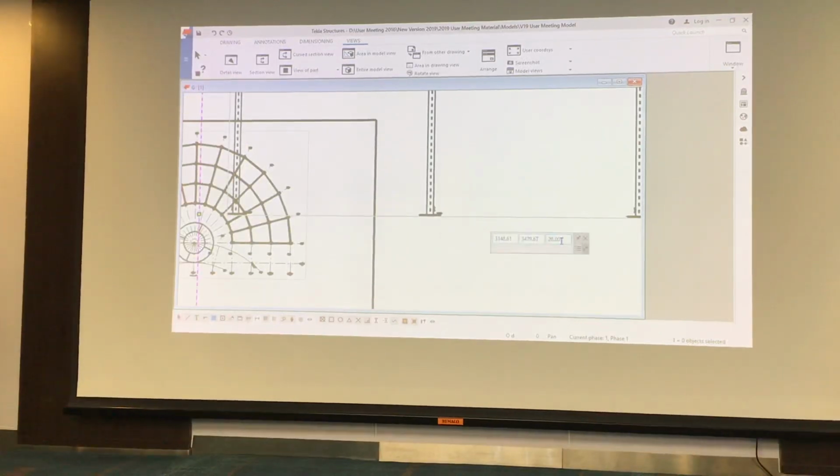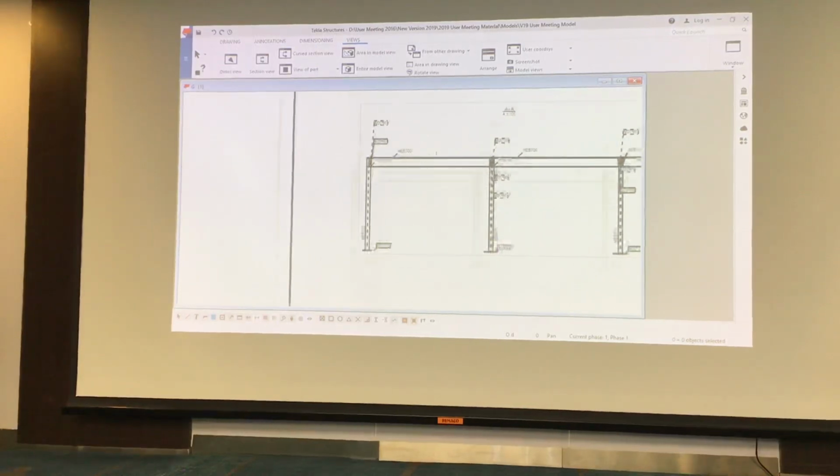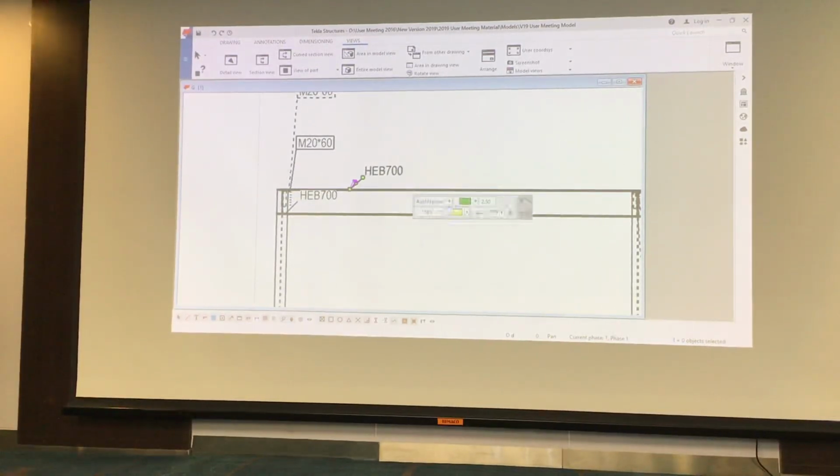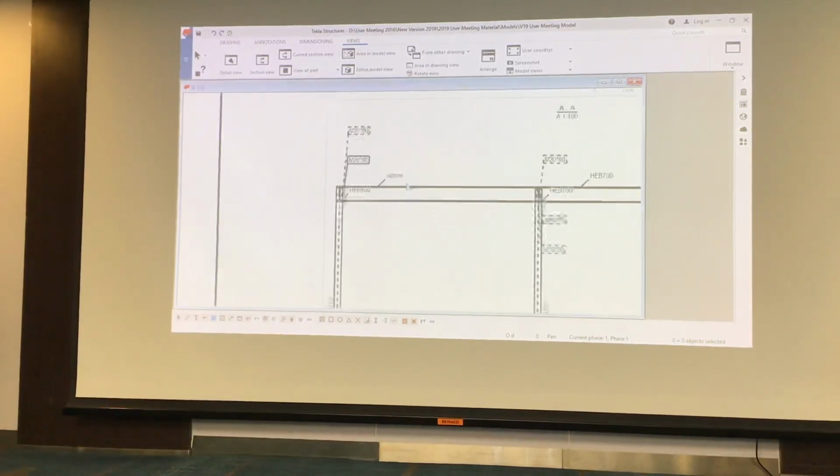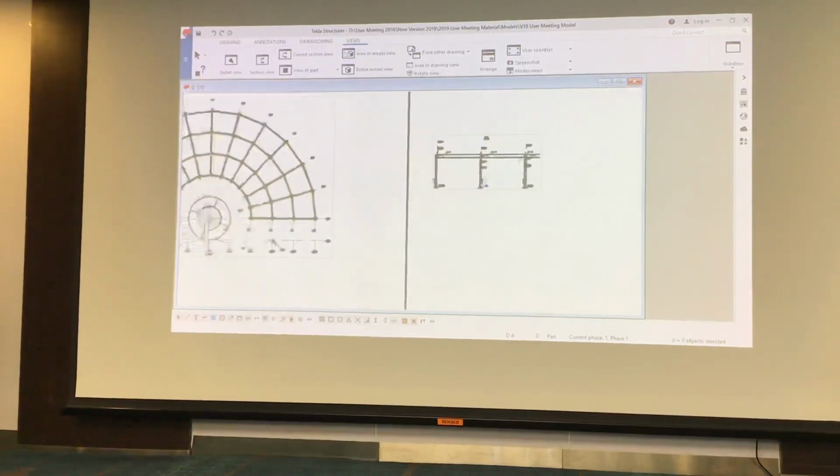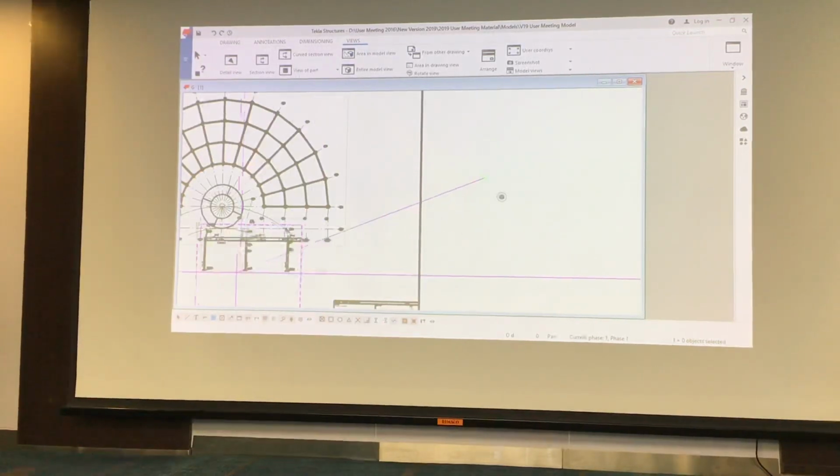Again, look, mini toolbar, click on this, scale 1 to 100. The mini toolbar works everywhere, look, so it's great. So it's a good way of setting this up and having things how you want it. I'd like that to be 2 millimeters. So it's a nice way of setting up the labels quickly on here. And again, pick that up, move it into here like this.